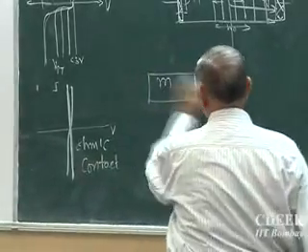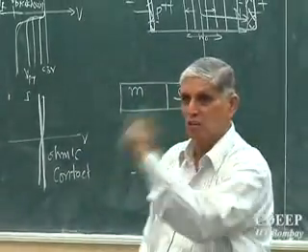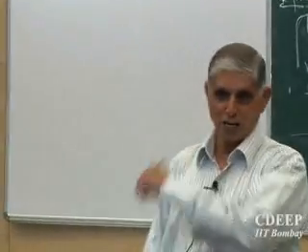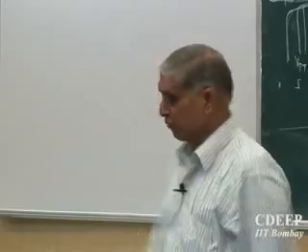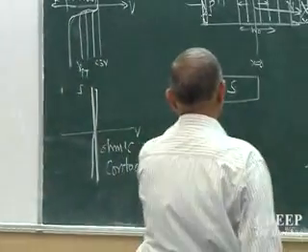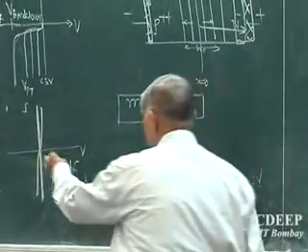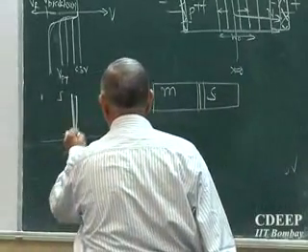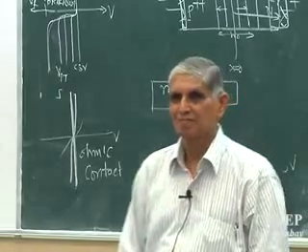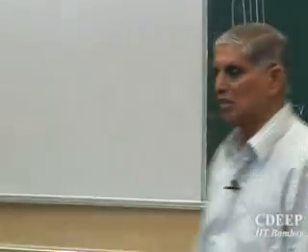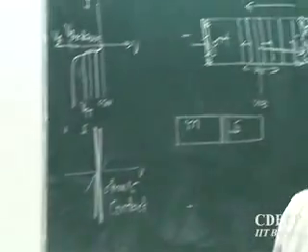So the junction should be so quick that it should allow all carriers to go across metal semiconductors, then only you can have a ohmic contact. If it creates a barrier, let's say because of something like this, then this will be same as like this. Is that clear? So my worries are how do I make a good contact? So let me first quickly look into a contact.